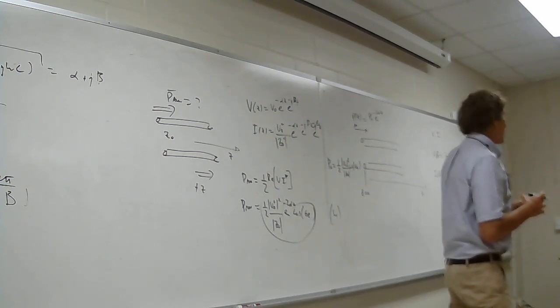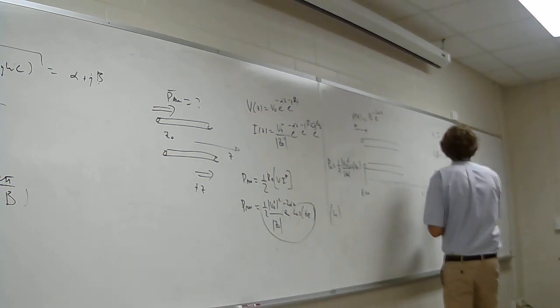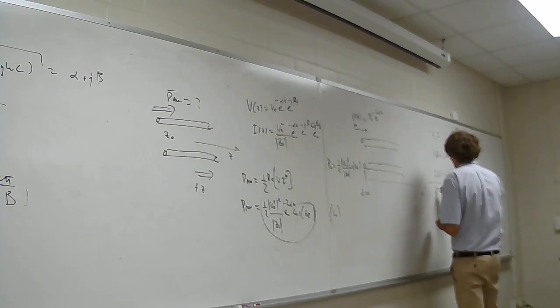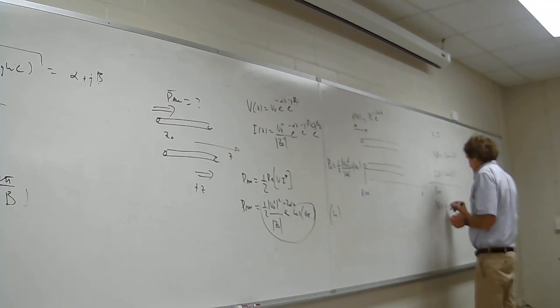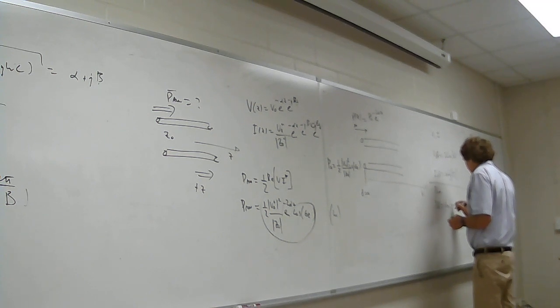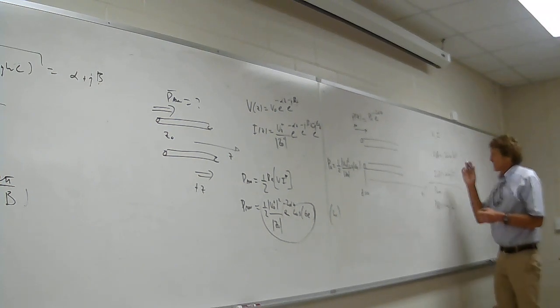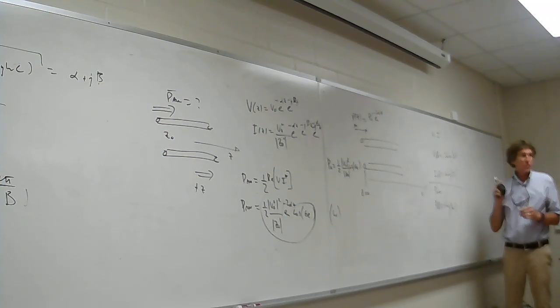But when you talk about power, then you would say the power in dB, this is a general form, is 10 times the log of the power that's actually going to be in watts, or the linear value. There's a 10 there, not a 20. You all remember this? And these are log-based 10s.